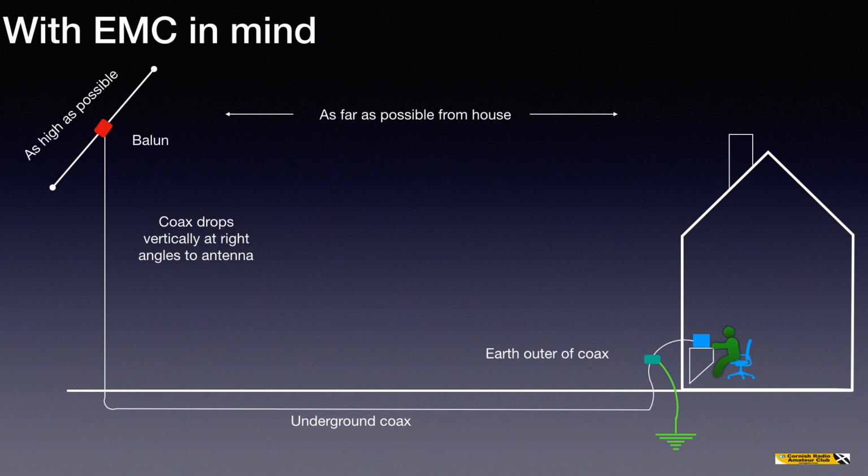Also, you need to look at the safety section, or the safety video, which will be produced, as well as read carefully the safety section of Foundation Now, so that you understand the implications of having PME supplied to your house, protective multiple earth. If that's the case, you do need to take some special precautions with regard to the RF earth.